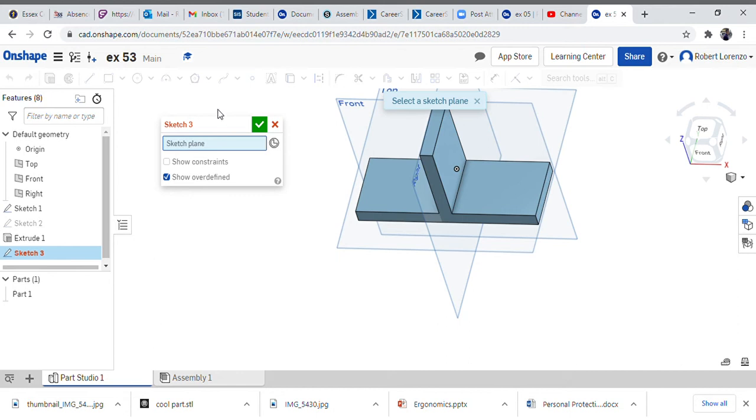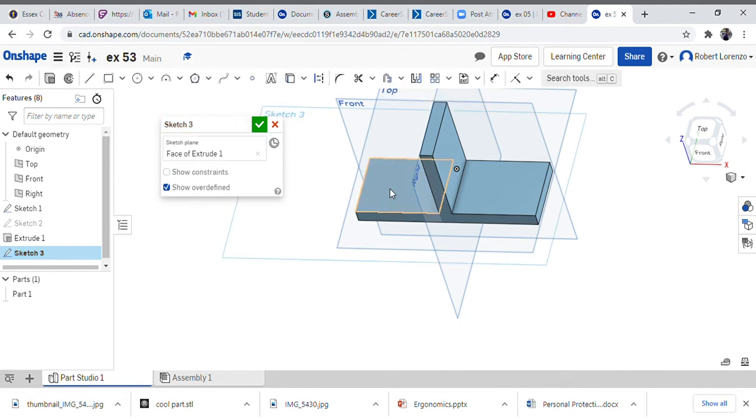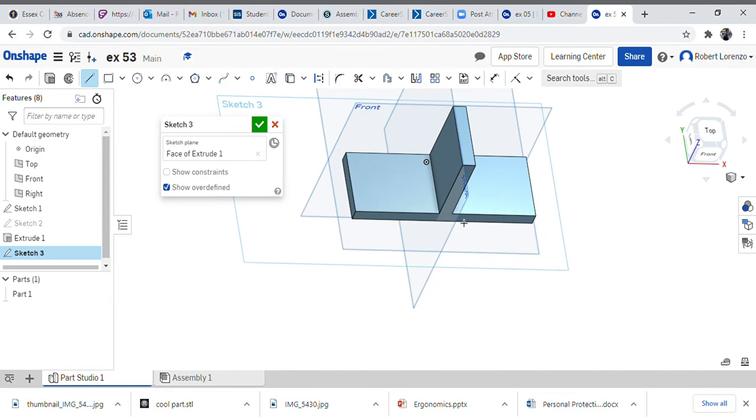We will do it in its entirety here. So new sketch, I'm going to click this surface, take my line, and just rotate around so I can clearly see where I'm clicking. So I want to be right in that corner and draw a line over 40 millimeters and straight up again. Make sure it's orange, 25.